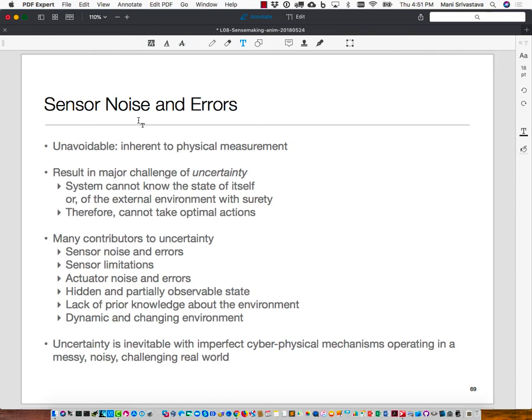So this first issue is simply that of noise and errors. Sensors are noisy, because our underlying electronics is noisy. I talked about earlier when I was talking about radios, that when radios detect a bit, they'll collect energy from the received signal, Eb over N naught, so energy in the received bit, and then they make a decision that a bit coming in is 1 or 0. All sensors operate like that. They are monitoring some signal for a short period of time, and then they decide, is the value this or that? That's what they are fundamentally doing.